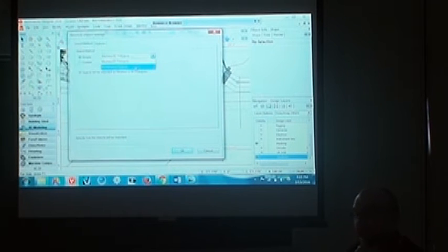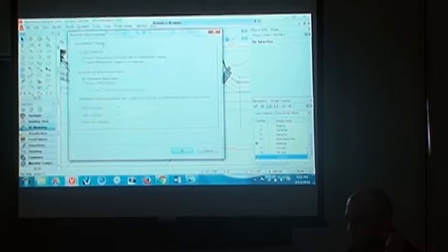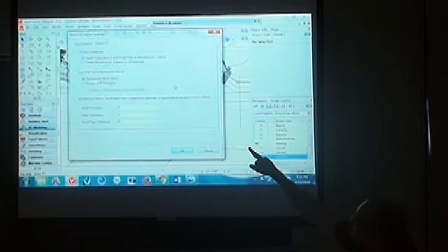That can be handy if you're importing something like a building or a model of a room from SketchUp. Then when you import it, you can convert it right into VectorWorks walls and windows and stuff. We don't want to do that for a car. The problem I ran into in VectorWorks 2013 is there's no way to import an object from SketchUp and maintain the materials: import transparency and image data as RenderWorks textures, create RenderWorks textures for all materials.